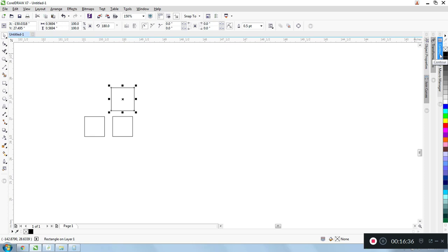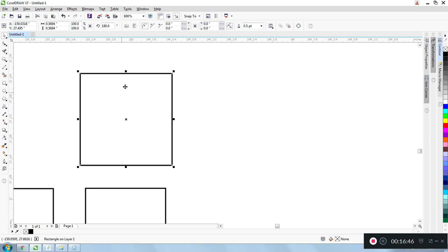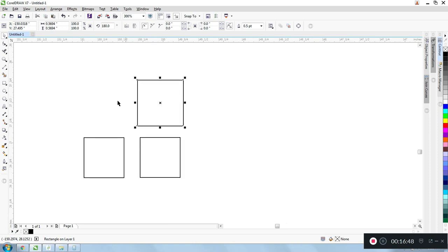So I might make my internal features of my design red and my external features black, and then when I select the order in which things are going to happen, I make red happen first, so that all my interior features are cut before the external cut.